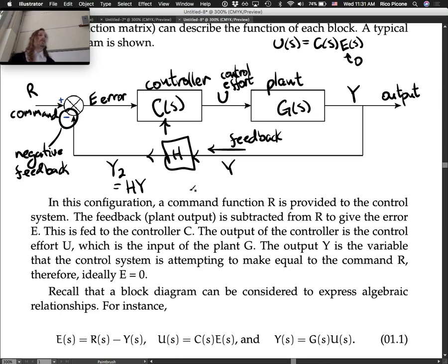Could it just be a converter, though? The input and outputs are different. If it's velocity versus voltage, and you need to convert back to something that's comparable to R. Right. So sometimes it's just a gain. Sometimes your actual measurement is in volts, but you have a constant that relates the volts quantity to a position quantity or to a velocity quantity or whatever it is.